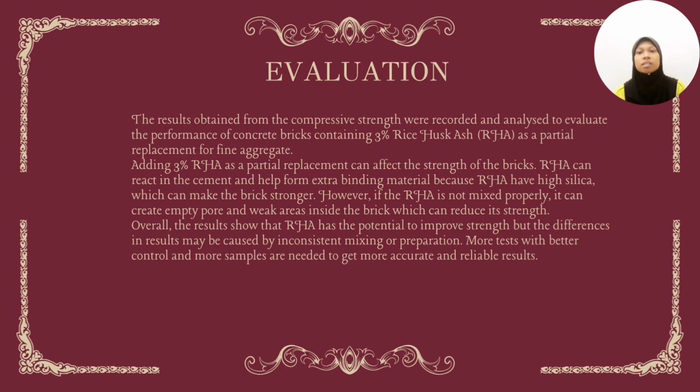However, if the RHA is not mixed properly, it can create empty pores and weak areas inside the brick, which can reduce its strength. Overall, the results show that RHA has the potential to improve strength, but the difference in the results may be caused by an inconsistent mix in our preparation. More tests with better control and more samples are needed to get more accurate and reliable results.